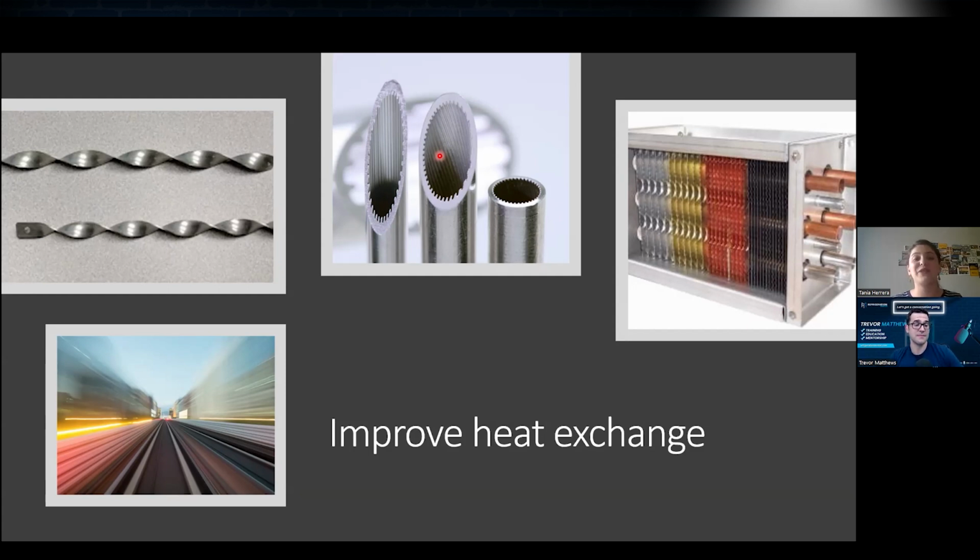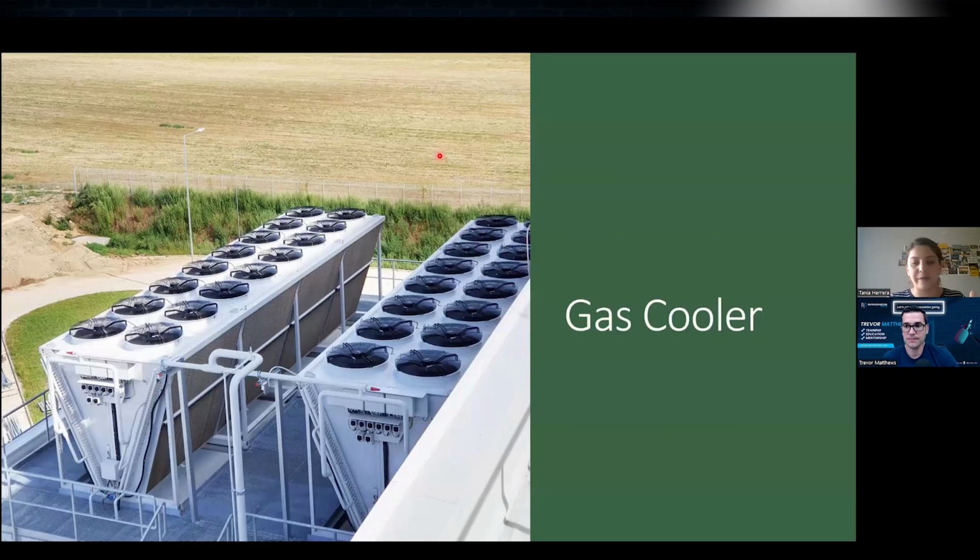So it's not free. Another thing we can do is increase the fins per inch, but as mentioned before, if it's an evaporator, it depends on the temperature, and if it's a gas cooler, it depends on the regulations, for instance in the case of California, or on the air pressure drop when flowing through the coil. So now let's get to what we are here for, gas coolers.